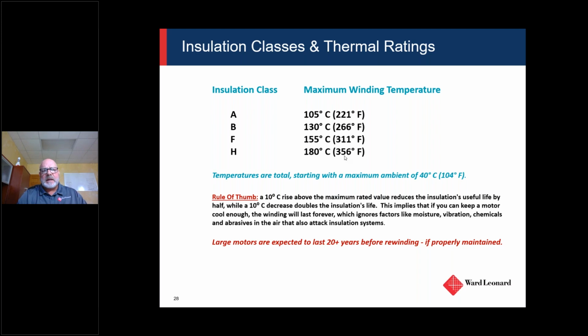And we have seen that a lot, where some people cheat that. They'll use Class H materials in the winding and construction of the motor, but use a Class F lead wire, and it's not a Class H motor at that point. It's Class F. But at any rate, Class H is designed for a maximum, and this isn't maximum over ambient, this is maximum operating temperature of 356 degrees F.